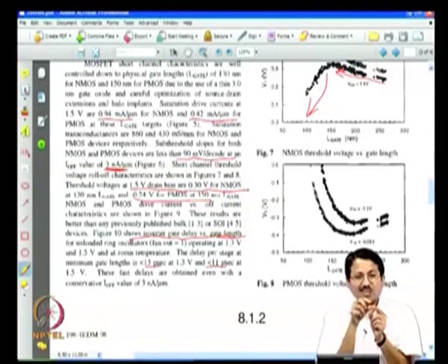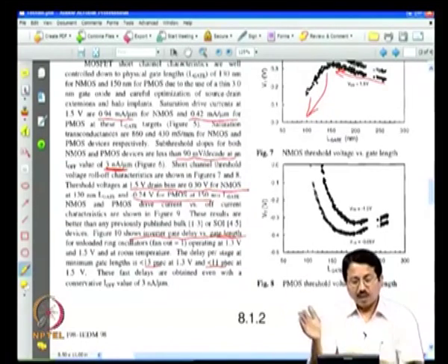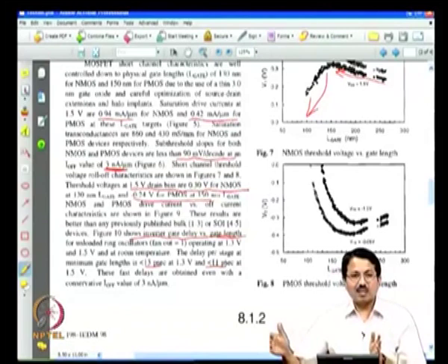So, you do not construct just one single inverter, because if you want to construct one single inverter, you will have to measure the time resolution of the order of picoseconds. What you do is that you cascade the inverters. A large number of inverters are in series.